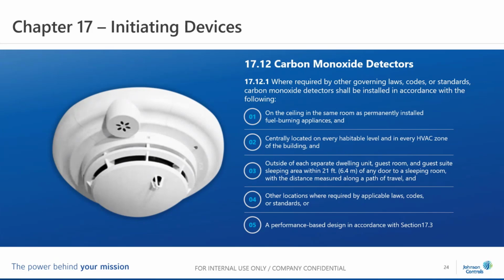For those of you that have done fire alarm for a while and smoke detector spacing, the 21 feet number should be very familiar to you because that's what we require for smoke detectors. The furthest point, the hypotenuse of the triangle, when you're laying out a device, the furthest away that it can be is 21 feet to a corner, a door, if you're doing elevator lobbies, etc.